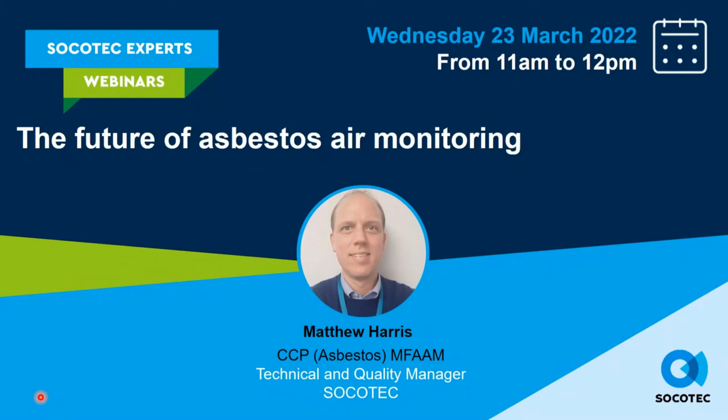Now, you may well be wondering what I'm going to talk about. Just to give you a heads up, on the future of asbestos air monitoring, our aims this morning are to highlight the recent changes following the release of the Health and Safety Executive's new HSG 248 Analyst Guide associated with asbestos air monitoring, and how we can perhaps achieve lower air test results when undertaking high volume sampling with our standard current techniques to help demonstrate best practice.